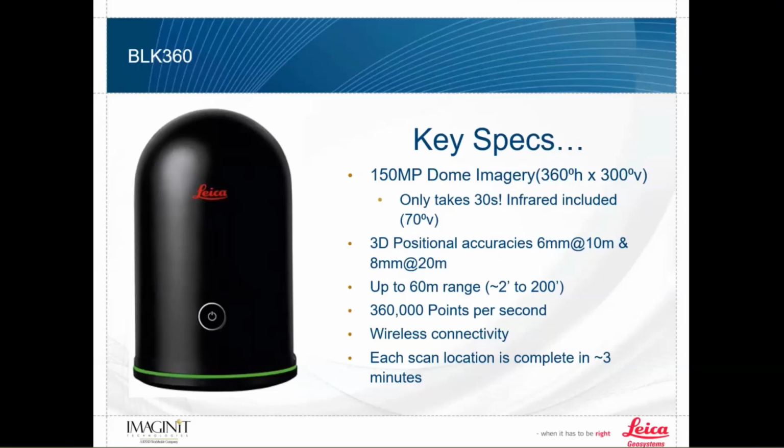Well, obviously, the scanner is not able to see beneath itself, so it can't get right underneath itself, leaving us with a little bit of a ring at the bottom where data is not collected. Now, if that data is important to you, it's a simple matter to pick up the scanner and move it, and scan that area again, and the next scan will cover any data that's missed.